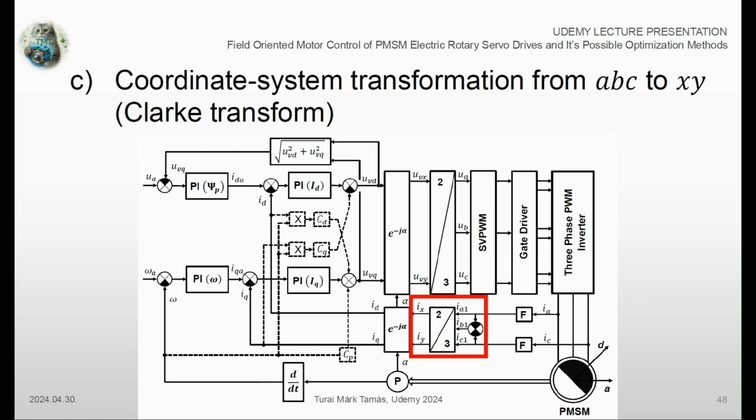The latter assumption means that we can neglect the need of filtering the measured phase current signals because no upper harmonics are present in them. However, we are going to implement a low-pass filter during the function software development part. So, all the necessary parts of the FOC algorithm are going to be covered altogether.